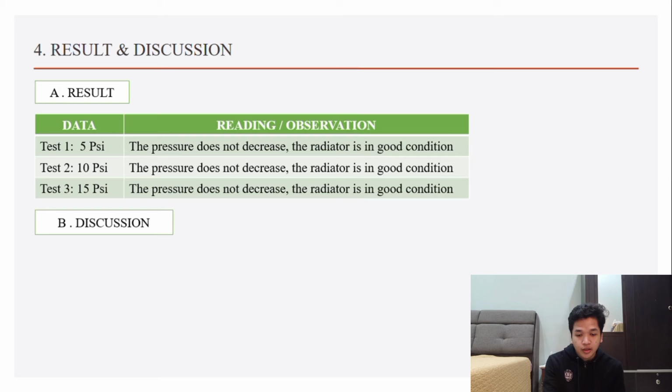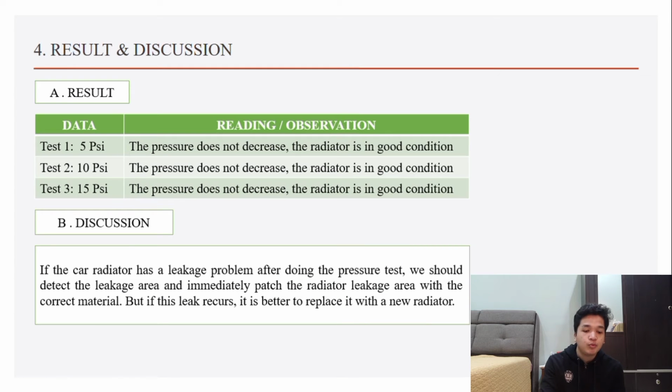And then, if the car radiator has a leakage problem after doing the pressure test, we should detect the leakage area and immediately patch the radiator leakage area with the correct material. But if the leak recurs, it is better to replace it with a new radiator.